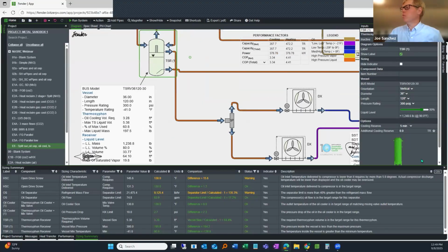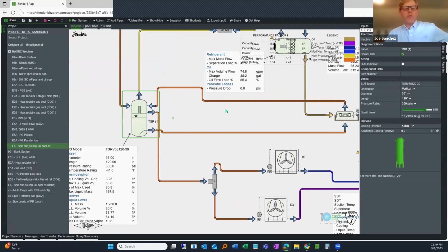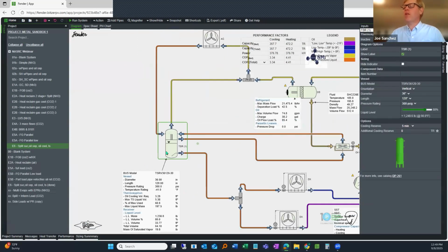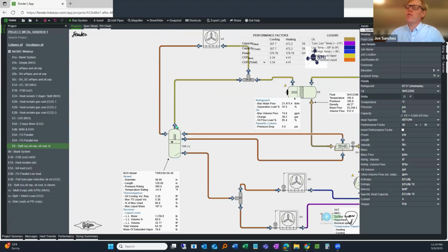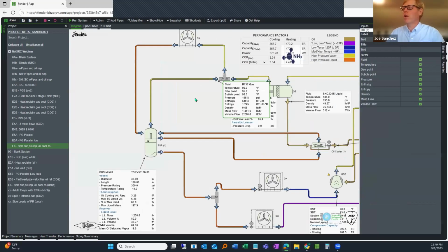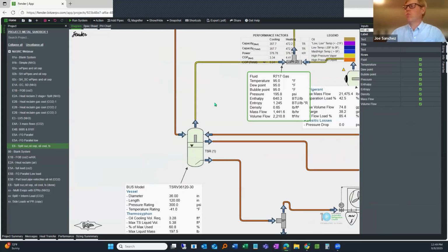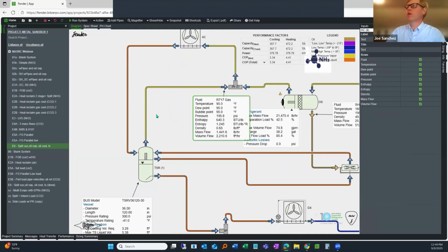And I like ending on this because it's a little humbling for me. When I was working in this and developing this for the first time, I actually could not figure out why the balance of this vessel wasn't working. And I realized I had never really paid attention to the thermosiphon vapor needing to go back to the start of the condenser. I've never really paid attention to that, but it's quite a lot of mass flow. I know the industrial system guys, of course, you know this, but me from the compressor side, I never had to worry about this, never had to think about this.